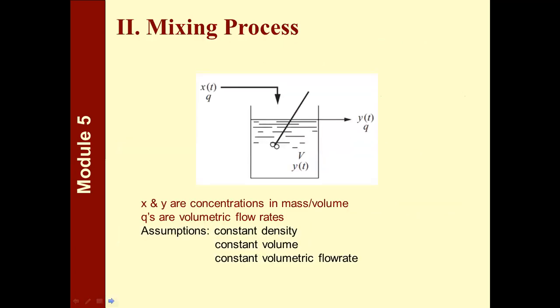So as for the mixing process, in here you have a fluid also in the tank. And these are our assumptions here, very important assumptions. It's at constant density. The fluid inside the tank at any time is at constant volume. And take note, unlike the liquid level system, your volumetric flow rate to and from the tank has to be constant as well. Because this time we're trying to measure the corresponding change in the concentration of the fluid leaving the tank to changes in the concentration of the fluid that is entering the tank.